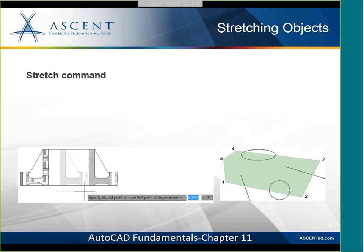Good. The difference with the stretch command is you can only use a crossing window for that stretch command, right? So it has to know what items it can stretch. If the item falls 100% inside of that stretch window, it gets moved. But anything that crosses that stretch window actually gets stretched. So definitely understand the difference there.